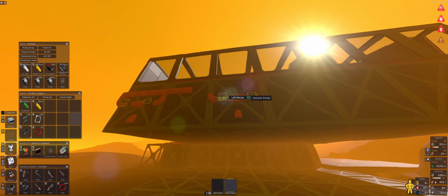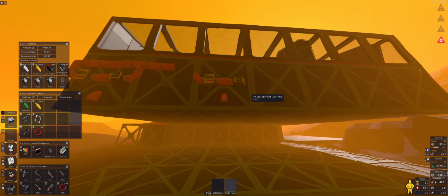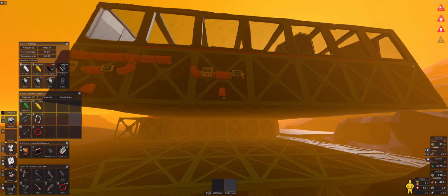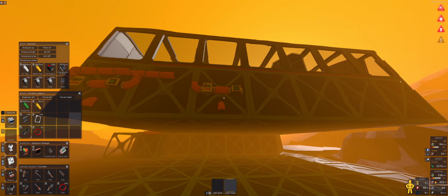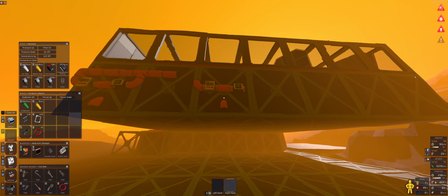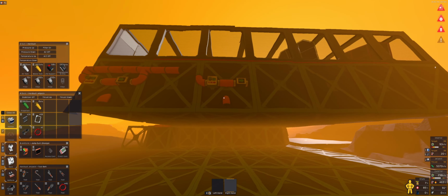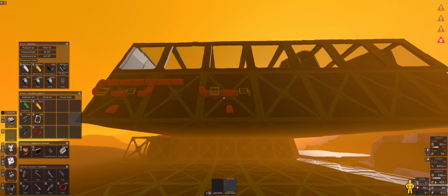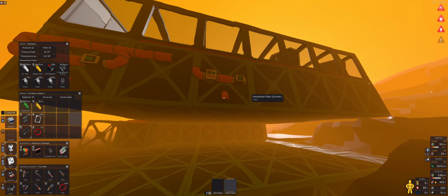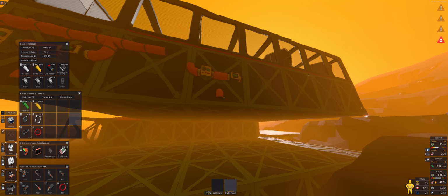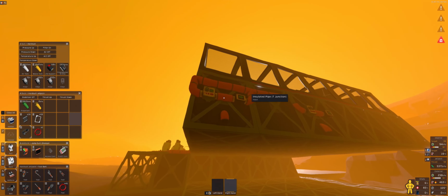I actually, instead of building this way, that there is this cold air going through the exchanger and then reflectively cooling down whatever I want, I put the other way around. I push my oxygen supply through the exchanger, and then whatever was left in the exchanger was actually solidifying and blowing up, right? This part of the pipe was blowing up. I did also something different. I actually paired them. So you could do something like, I'm gonna pair my just cold nitrogen with whatever I have and just let it be. That's even worse, right?